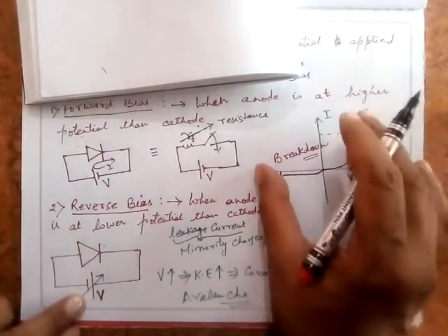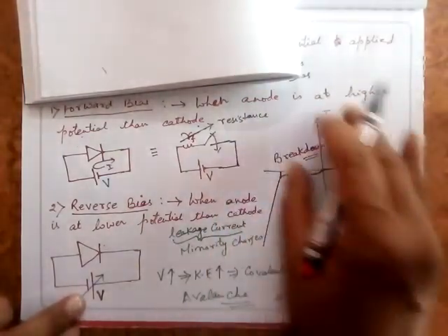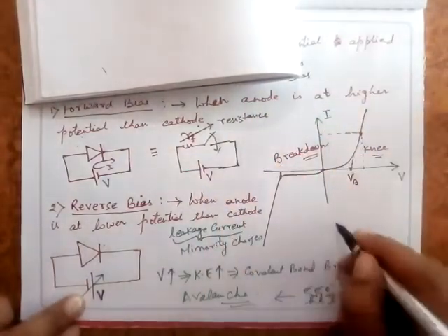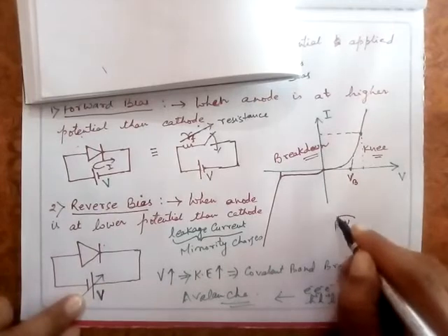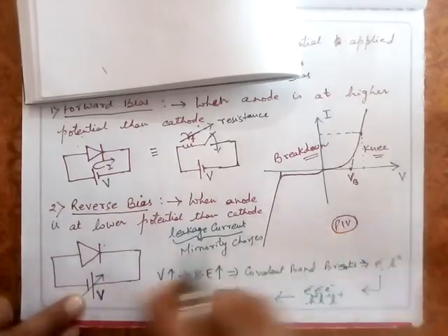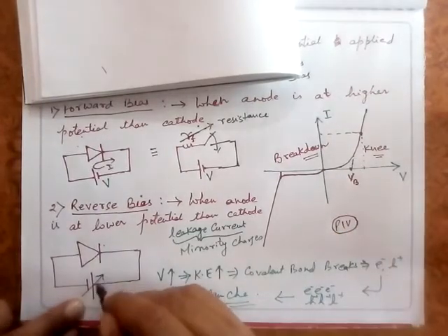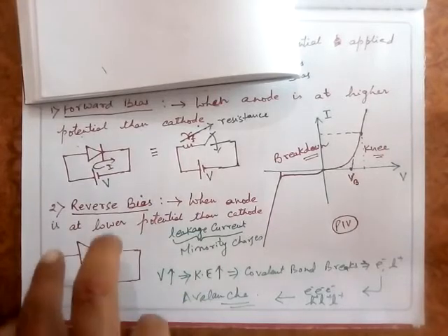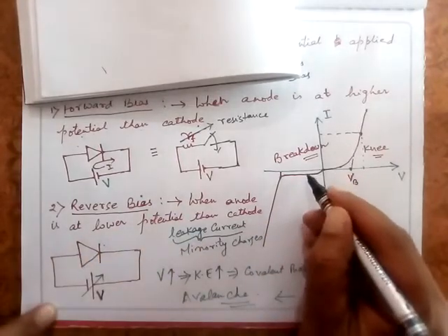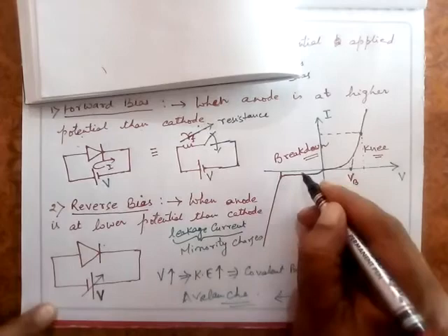In all the specifications it is mentioned what the peak inverse voltage is. This is also called the peak inverse voltage. That is, under the inverse condition, what is the maximum allowable voltage that can be applied to this diode. However, a small leakage current is flowing here. This current is the leakage current.